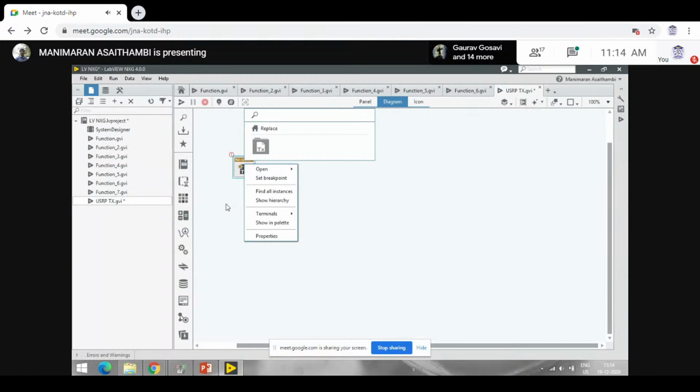So now what we are doing is data signal pushing. The same one I'm going to use as a waveform. So this is going to be the same waveform. I'll have one more copy. I paste it here. So this is a sine waveform. For IQ data, what I have to give is one should have a phase angle constant of 0. Now if you see, this is an I waveform, this is a quadrature waveform.